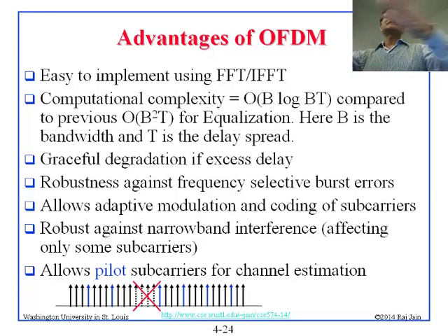Interference is when somebody else is transmitting at the same time and they're interfering with your transmission, right? So obviously you have to first take care of the interference, because interference generally is so high, noise is so low, right? So sometimes we say signal to noise ratio, sometimes we say signal to interference and noise ratio, SINR. So anyway, narrow band interference basically says that somebody else is transmitting but they are using part of the band, you can still continue your work.